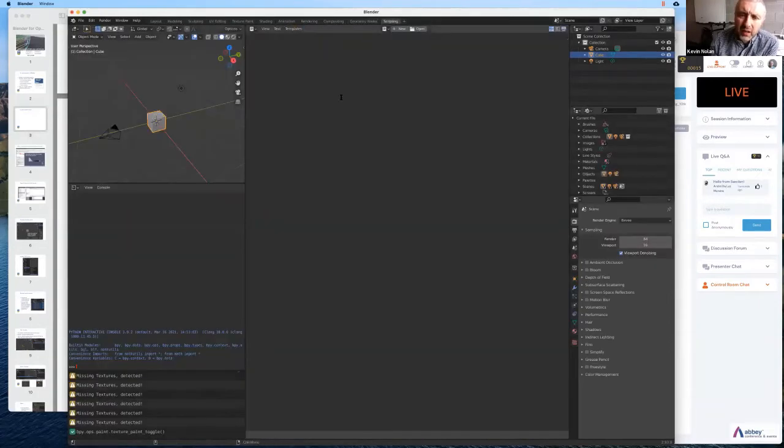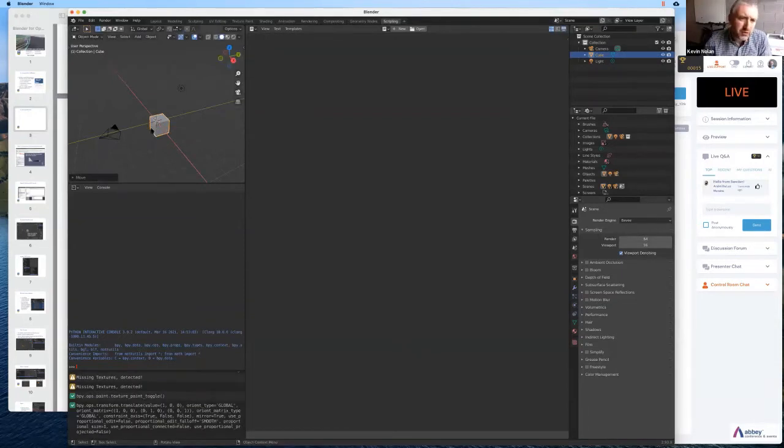And then finally, everything in Blender has a surfaced Python interface. So Blender is written in C++, but the entire UI runs on Python. So anything I can do, if I were to grab this cube here and do something with it, so G X 1 moves it 1 in the X direction, and that command that we can see here is written here as a Python script. So you can easily create Python scripts to create geometry or do whatever you like with Blender.